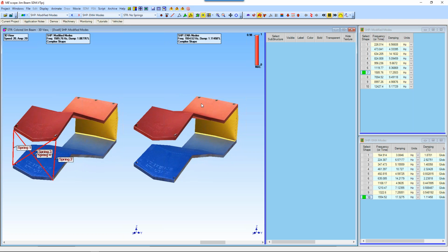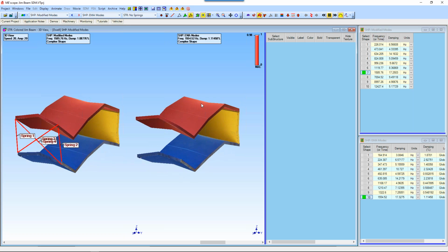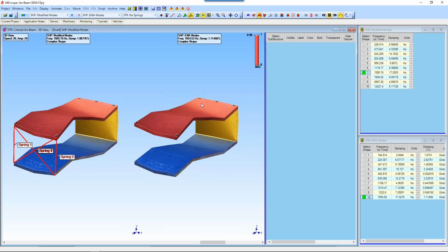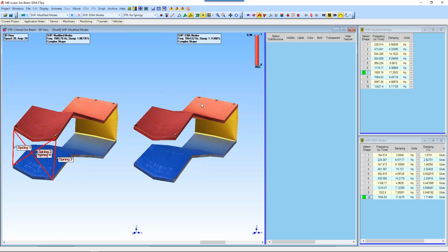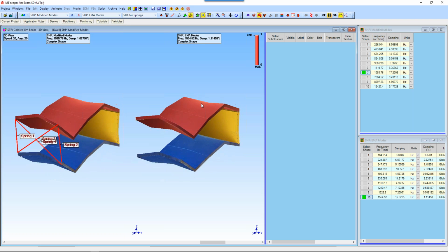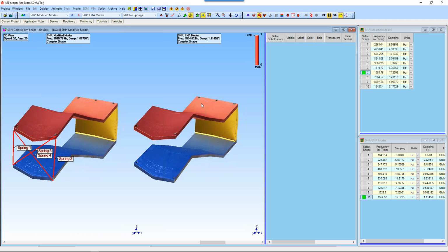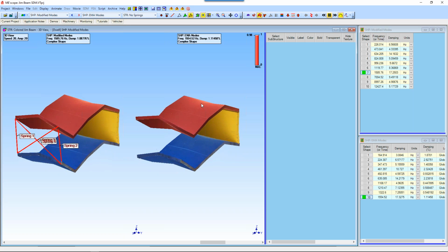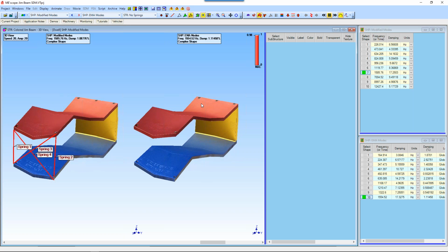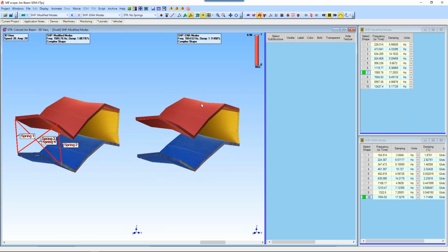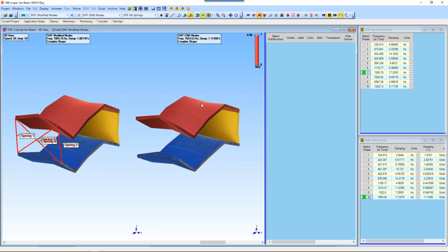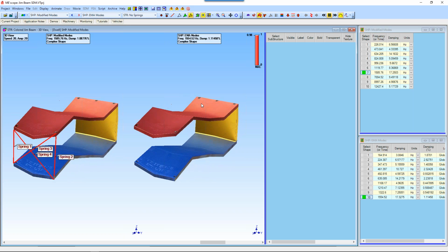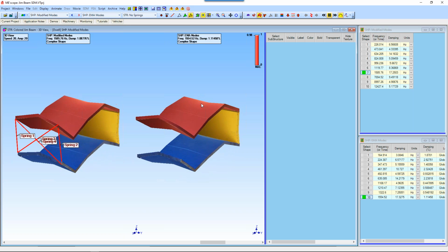Well, we've spent an hour together, and I wanted to show you the modal modeling and how we set that up, the different ways we can scale our data. And then once we have a good modal model, we can go in and use SDM, use the modal sensitivity to look at how sensitive the structure is to performing these modifications. Fairly simple structure.